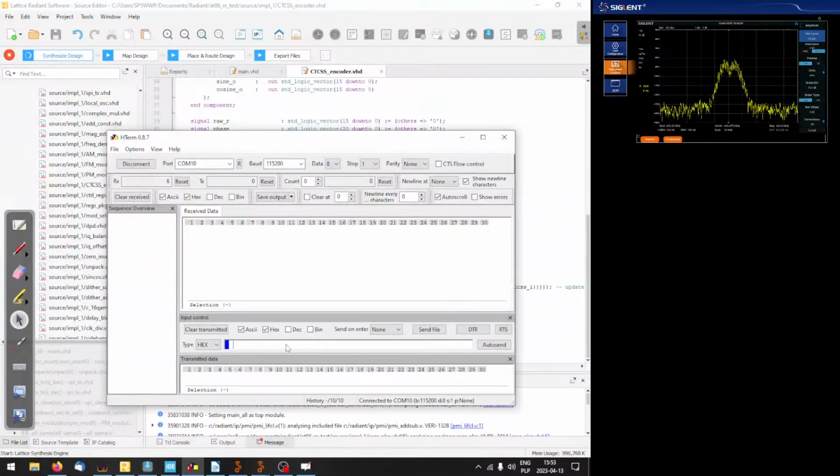One of them is used for the SWD programmer, and the other one is the target. So the UART of the first one is connected to the UART of the second one. So you don't need any additional cables to use the UART of the STM32 that is the target.